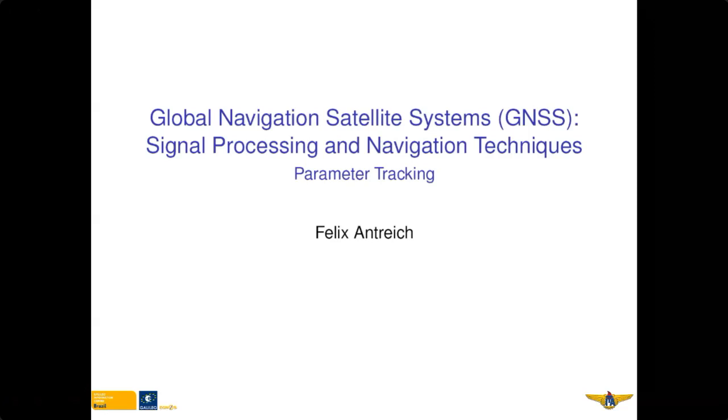So let's start getting into this. First, we want to understand what the objectives of parameter tracking are. First of all, we want to refine the estimates of Doppler, carrier phase, and time delay that we got from the acquisition. We have been searching for Doppler and time delay in the acquisition, but as we have seen with the parameter alpha, we can also immediately derive an estimate of the phase with an ambiguity of pi. Because of the symbols, we can also derive a phase estimate to initialize.